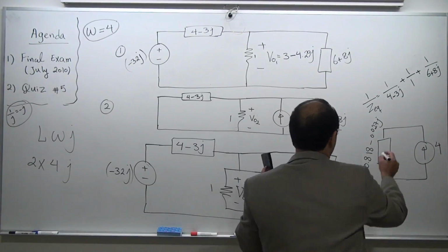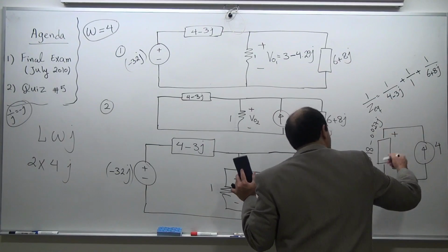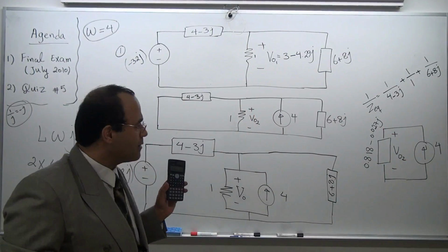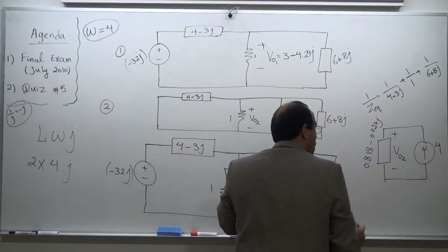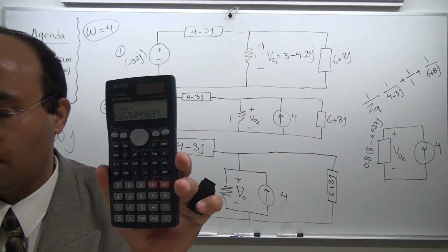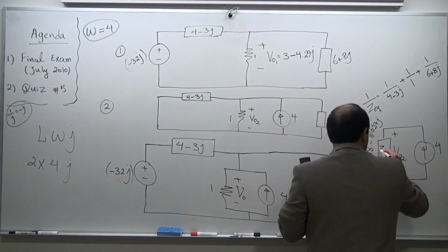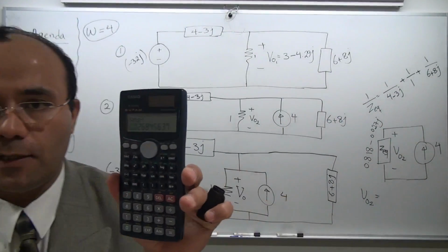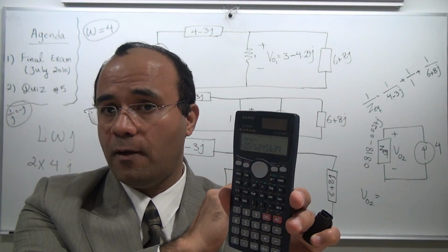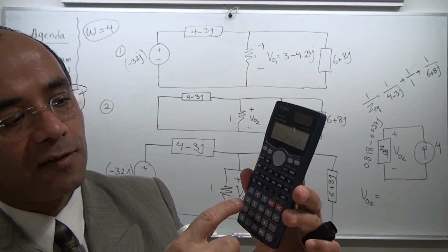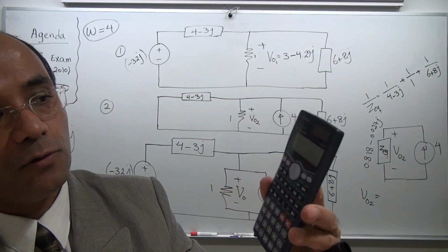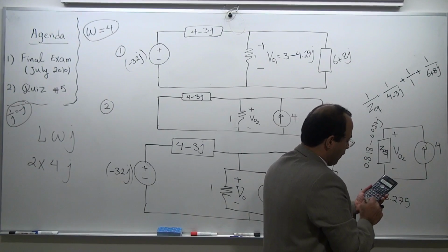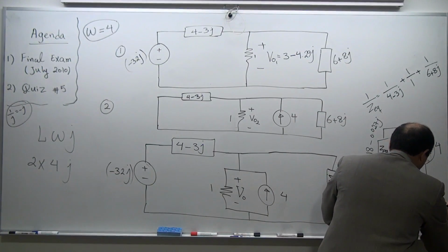So when I want to find this voltage, remember, that's the plan. This is going to go in, hit the resistor on top, creating the plus minus, the same polarity I had, and that's going to be my VO2. The answer with all the details is in my calculator. So all I need is this Z equivalent times 4, and that's going to be my VO2. I didn't do anything, although I wrote some 2-3 digits on the white paper for the examiner to see. I simply say times 4. It's going to be answer times 4 is equal to, that's going to be 3.275, and then shift equal minus 0.107j.